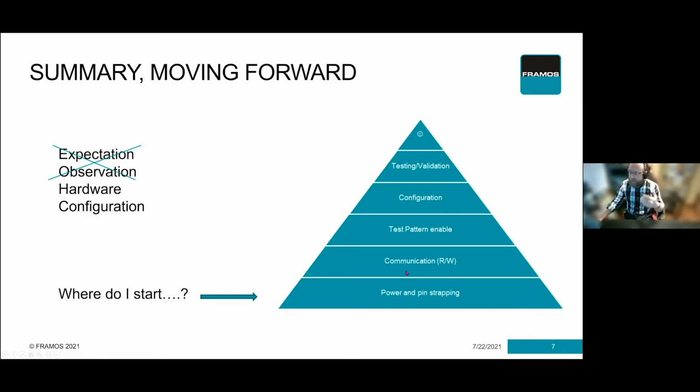Are we looking at a fundamental error where we're not receiving a frame at all, or we could be receiving a frame, but the FPGA, for example, is not actually processing it. So locating it, because again, this is a vision system, and because we have the image sensor and all this ancillary hardware just to make it work, we can't view through, we have to view our bug through that other hardware, where there could also be a bug.